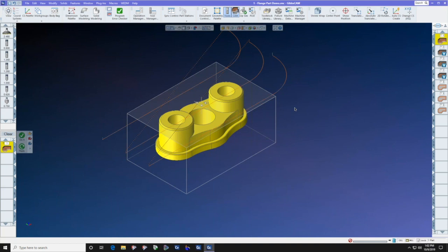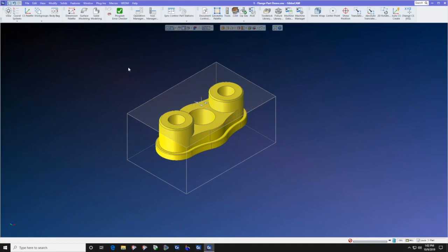In other words, the mouse that you see on the computer right in front of you is a perfect example of a 3D solid, whereas this part that we have here in front of us can be machined completely in a 3-axis vertical milling machine. And that's exactly what we're going to do. We're going to go through this step by step, and we're going to talk about importing a solid model. Importing a solid model sounds like a terribly dangerous thing, but it's actually very simple.